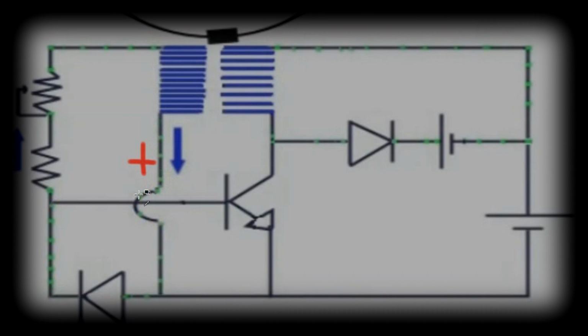So positive signal would have no path to go. It gets blocked that way because of this gate, but it can go this way, back to the base. And the negative signal is curiously also on the base. The negative trigger winding signal is on the base with resistance.